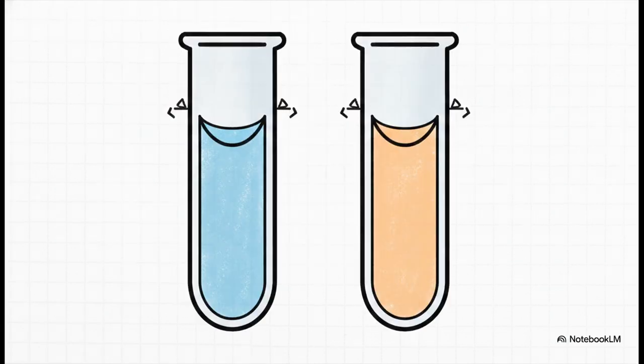And what happens when these fluids actually touch the walls of a container or a pipe? Well, VOF can model wall adhesion and contact angles. This allows us to accurately simulate wettability effects, essentially dictating whether a solid boundary is hydrophilic, meaning it loves and absorbs the liquid, or hydrophobic, meaning it actively repels the liquid. Capturing this is essential for creating realistic meniscus shapes in your simulation.